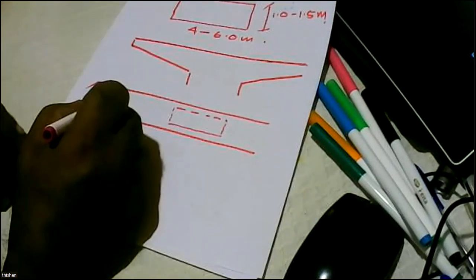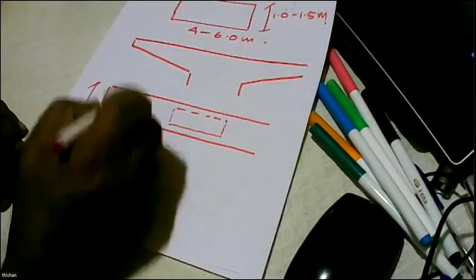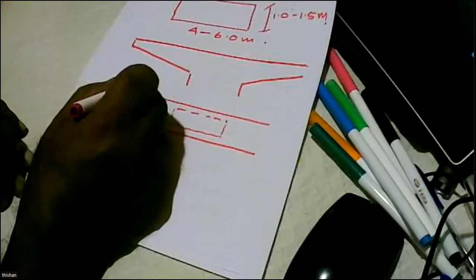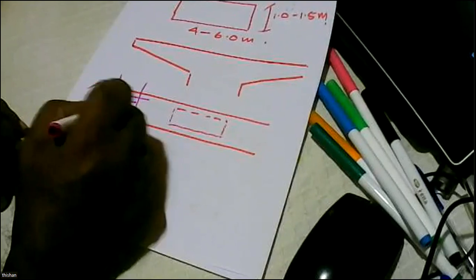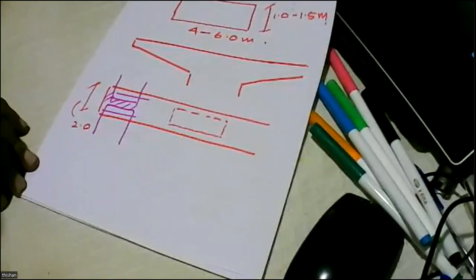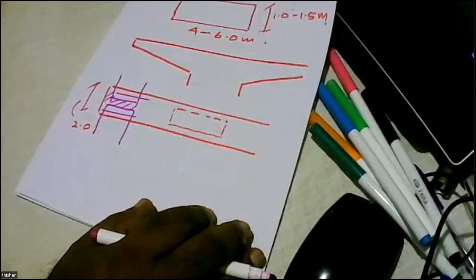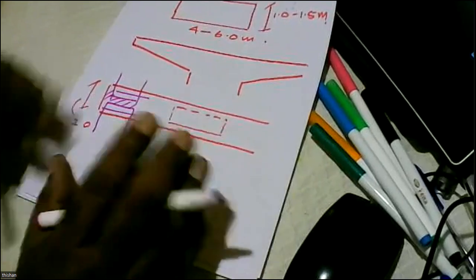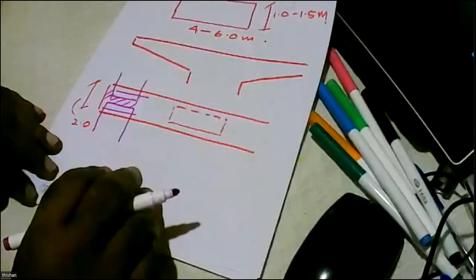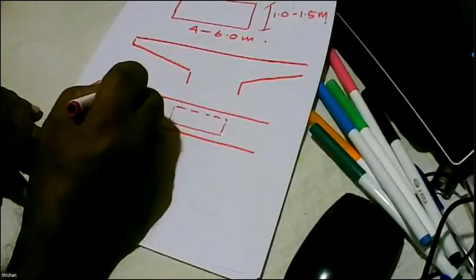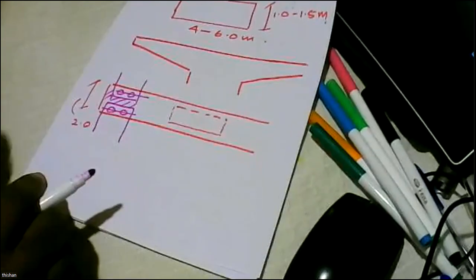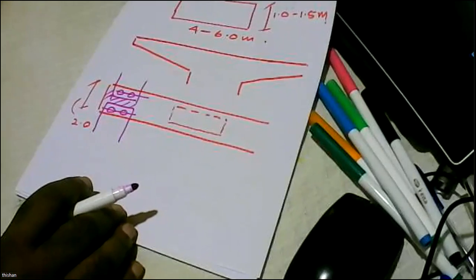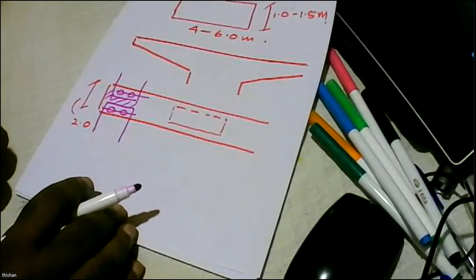So the beams might come like this. And then you have to create a diaphragm connecting them. Depending on the type of connection, you might have to do something to ensure that the bearings can be properly placed, and also this continuity is taken into account. So which means you need space.